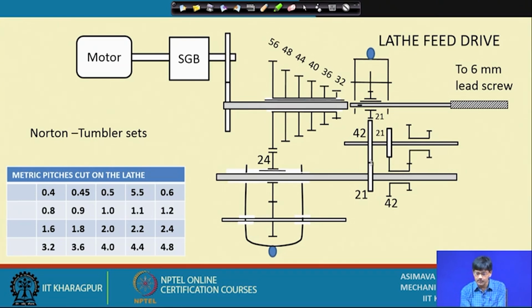First of all, we have kept two gears of 21 and 42 teeth, so that the RPM is halved here. So, if you get 20 RPM, you will get 10 RPM here. But once again we have put a 21 gear here and the same knot and tumbler arrangement, so that again we remove that half, and this is 1:1. But if we move this and connect it up here where the number of teeth is 21, again we will get a half. That is fine. So, 1:1 here, and if we shift this and connect it to this one, we will get half here.